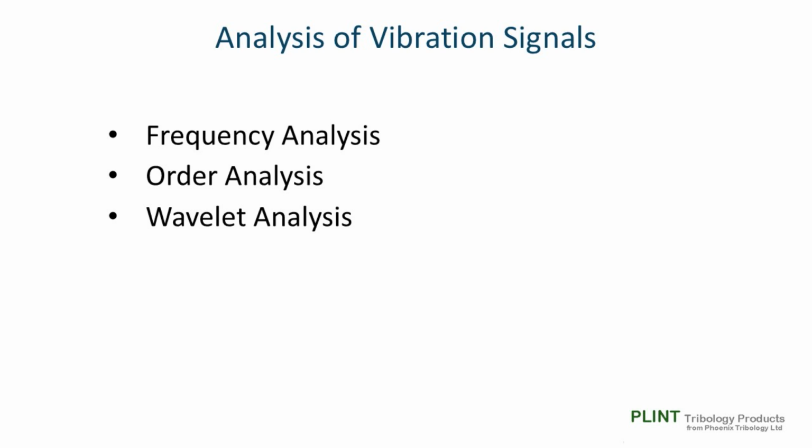It is not suitable for signals whose frequencies vary over time. If we have something like a bearing rotating at a given speed, it will generate a signature frequency or frequencies. We might sensibly decide to focus on these specific frequencies for monitoring and analysis purposes.